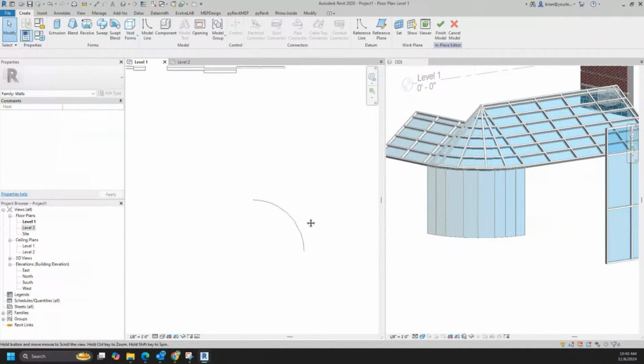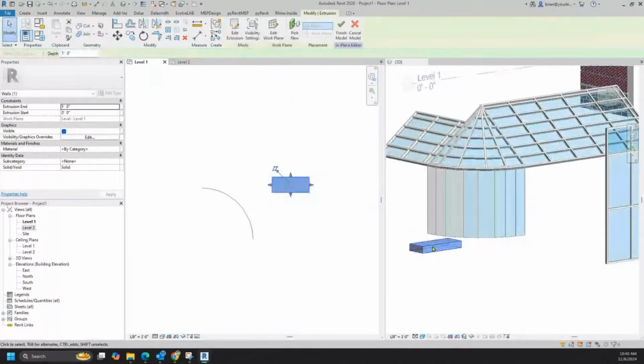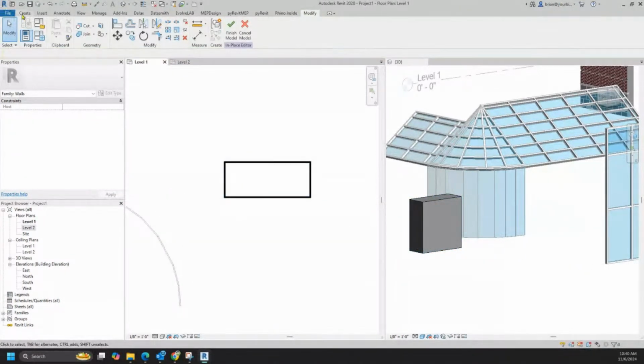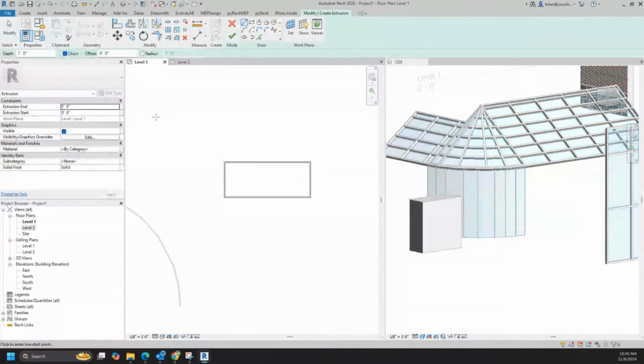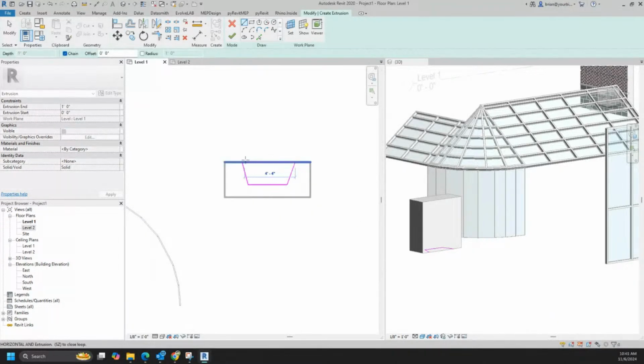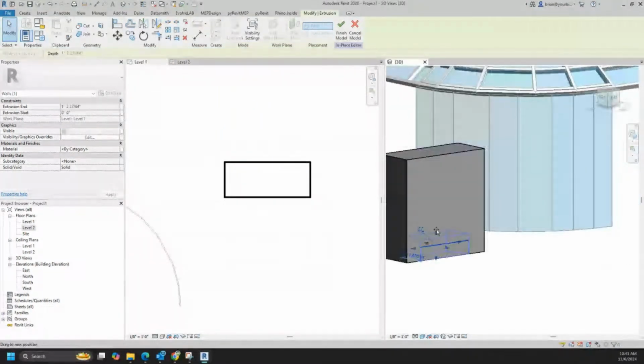So if we're right here, if we did an extrusion for this fireplace, and it might look like that, finish. The idea is then you could stretch it up. Then you could come back and create another extrusion. And I'll be honest with you, and I'll show it to you after I do it, but you've got to shape something like this in your fireplace, right? Oh, and it tells me that I didn't finish drawing my shape, because remember, it's got to be closed. Now I could draw it, then I would take this thing up.